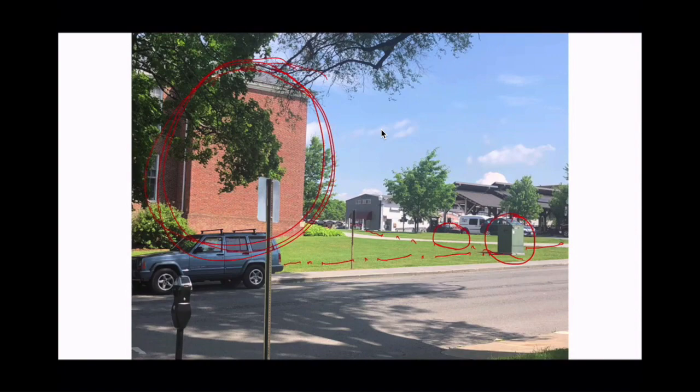So the switchgear is these kind of cabinets that basically have a switch outside the cabinet that disconnects the real breaker inside the cabinet. And the switchgear is always located right at the moment where the electrical line goes into the building. So it's always upstream of the rest of the building, because you wouldn't want the fireman to turn off the switchgear and think everything was off, but there was something upstream of that switchgear that was still live. So you want everything downstream of the switchgear to be turn-offable by the switchgear itself.